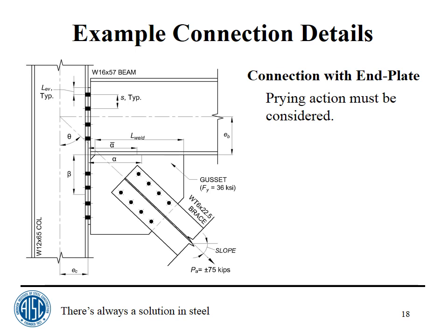I don't think that there's anything specified in that regard. I think various fabricators have their own techniques. I mean, columns generally are perhaps a bit overrolled. Maybe they're underrolled, but not by that much. But then you've got tilting of flanges and all of that sort of thing to deal with.